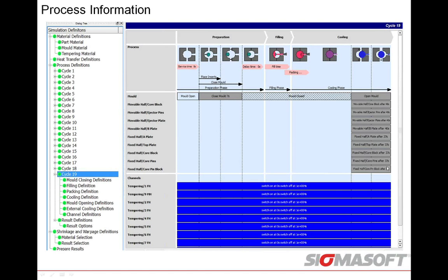You can see here that we have our mold open time specified at 40 seconds for the movable half, 37 seconds for the fixed half. The idea here is that when that mold opens, the part is still in contact with the movable half for an additional 3 seconds. So again, it's very important, and it goes back to what I keep saying, not to sound like a broken record: calculate more and assume less. If that hot part is in contact with the B side or the ejection side for an additional 3 seconds, it's touching that hot steel or that cold steel for an additional 3 seconds. That's going to impact your warpage. And then going through and specifying all the different parameters here, your cooling and so forth. And you can see here I have my multiple cycles specified.